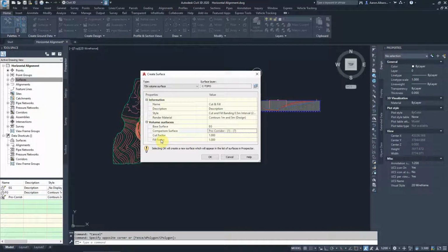We try to do our engineering compaction for the fill material, but it's almost impossible to reach the actual natural status of the compaction. So I will allow about 10%. That tells us that when we cut about 1 cubic meter, that will require a volume of 1.1 cubic meter to be filled in.